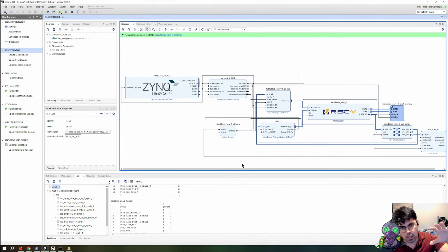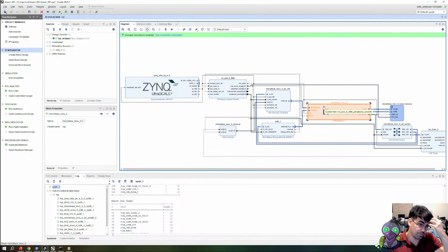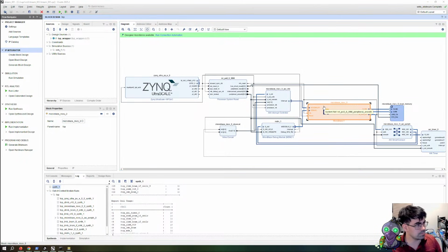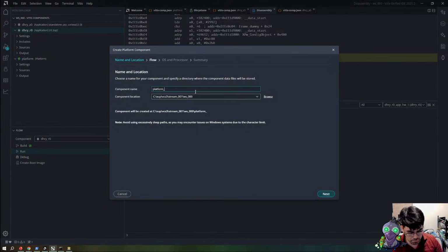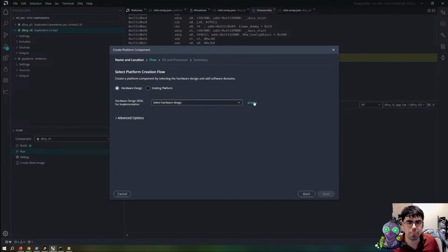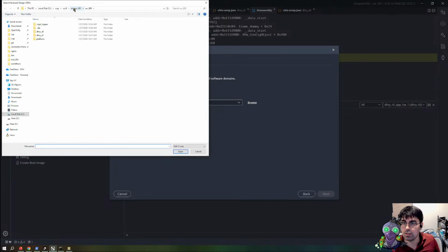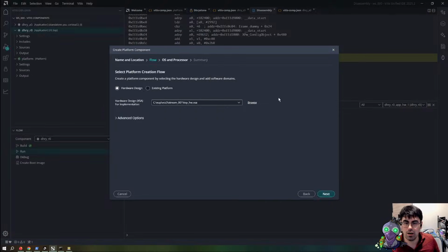We have just built the application for the ARM processor, application A53, and the real-time processors, the R5 processors. Now we are looking at the MicroBlaze, which is going to be a soft processor implemented on the system. So in Vitis, we're going to go ahead and do a new platform specifically for the MicroBlaze, which includes the bit file. And we have the top hardware.